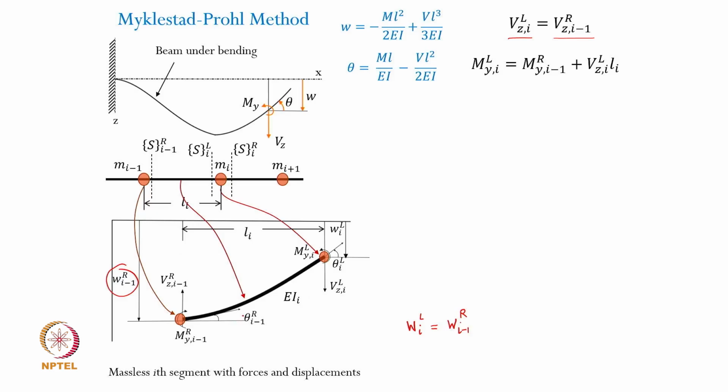From that I will have to subtract the deflection. It's not a deflection, but it's this amount of displacement because of the existing slope at this point, isn't it? That much displacement has to be reduced from this deflection, so that I can reach W_i L. Okay. So obviously I will have to subtract from this how much,